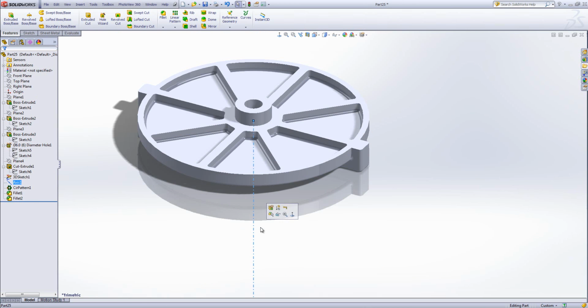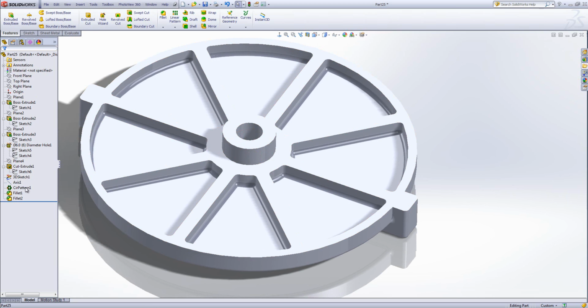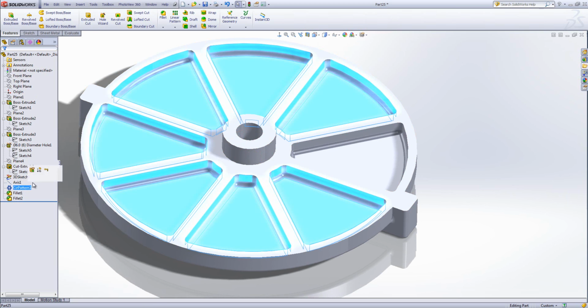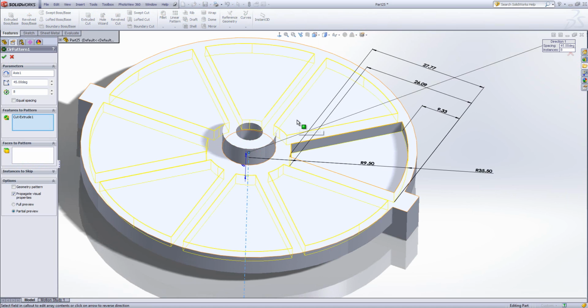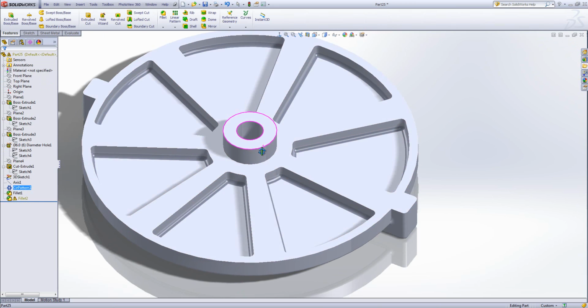So having built up something like this, you could then go through the model and make certain changes. For example, you could go into the design and you could edit the amount of items in the circular pattern. You could reduce the amount of items down to something like 7. Just make sure equal spacing is turned on. It's going to cause a slight problem for the fillets, but then you can just make slight adjustments for those.